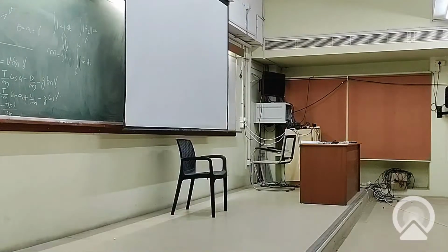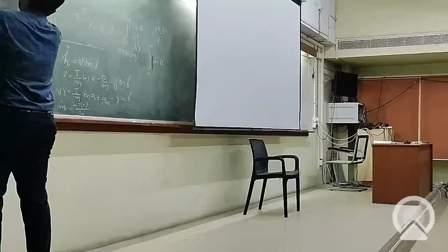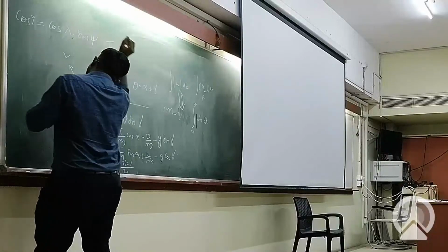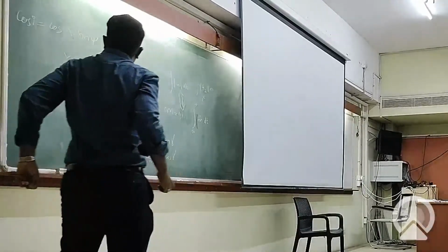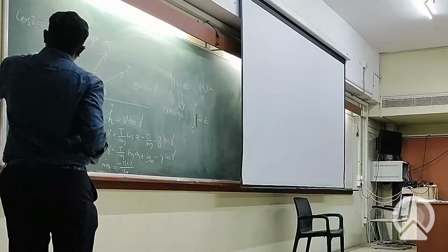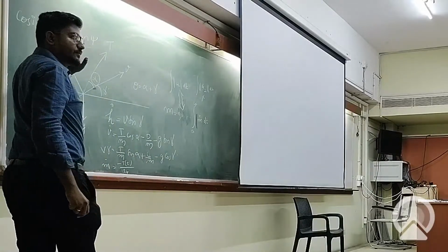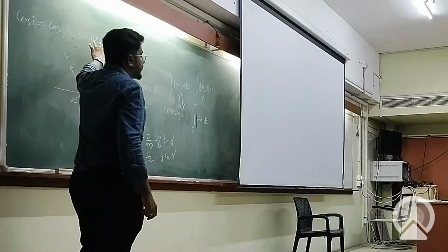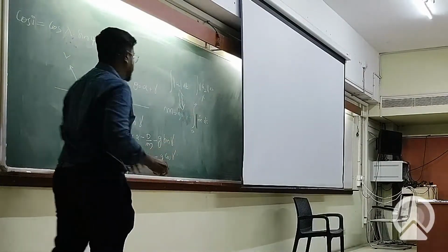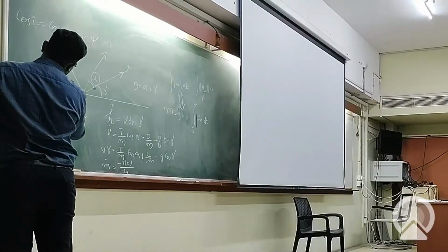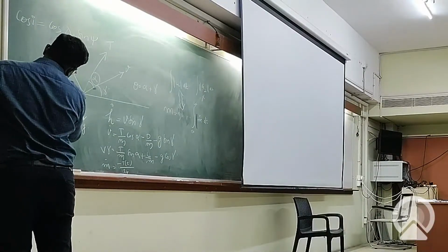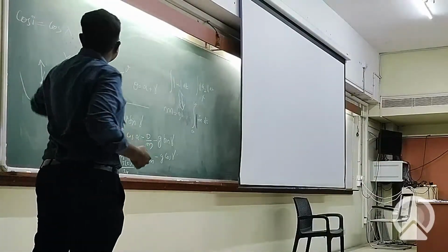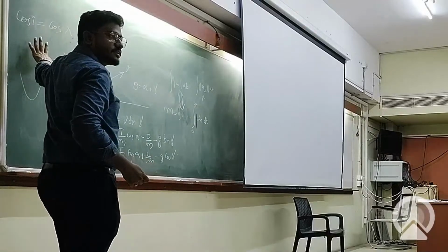Cos i is equal to cos latitude into sin of the azimuth. Basically, the inclination that you can achieve in case of planar motion is a function of the latitude of the launch point and the direction in which the launch is made. Say we have a launch pad here, with the azimuth measured from the north, and the latitude, of course. These two determine the inclination.